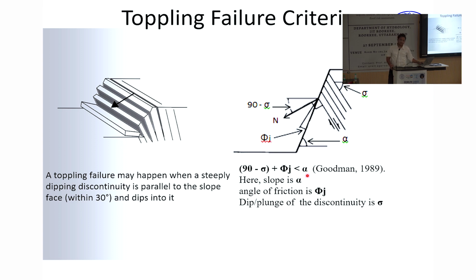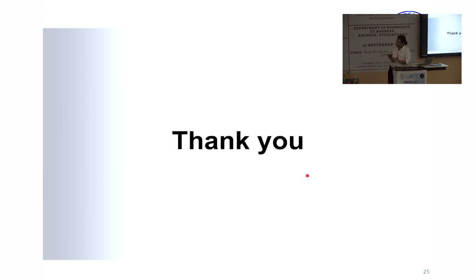It's very simple, and believe me, determining these angles, except the angle of internal friction, for which we need to do laboratory testing, is a very trivial job. Determining the angle of slope and the angle of discontinuity is very easy. A trained structural geologist needs maybe 5 seconds to do it. But you have to go in the field. Thank you.